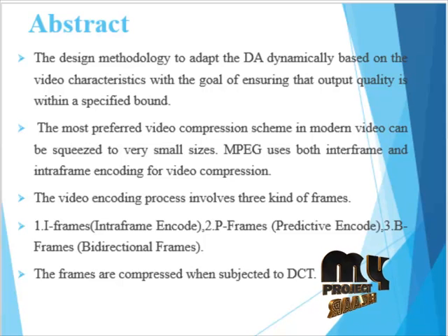Different approaches for approximation include error introduction through voltage overscaling, intelligent logic manipulation, and circuit simplification using CAD based optimization techniques. These methods can simplify implementations by replacing adders with approximate adders, or by deleting some of the transistors.